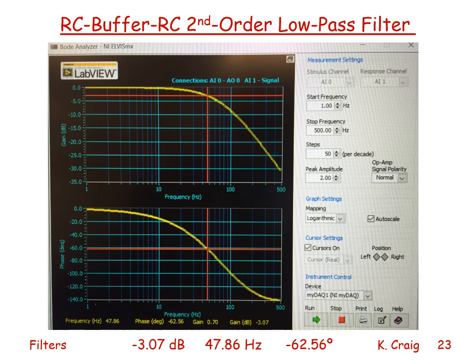And the result is my Bode plot here. I still see at low frequency my horizontal 0 dB, at high frequency minus 40 dB per decade, at low frequency the phase angle approaches 0 degrees, at high frequency it will approach minus 180 degrees as the frequency is increased, and the minus 3 dB point is now at a different frequency.